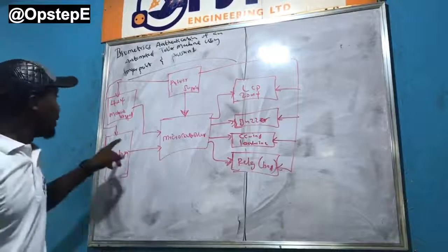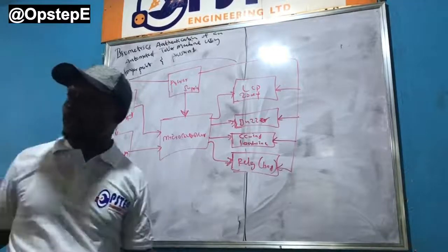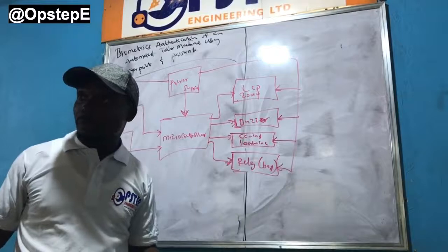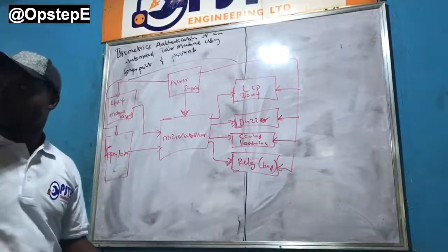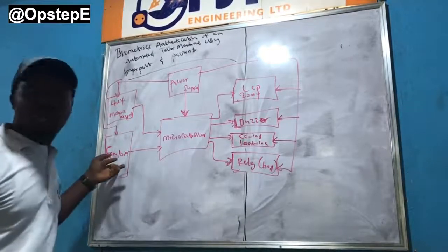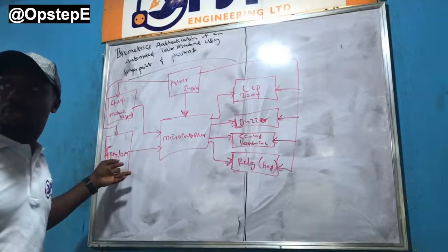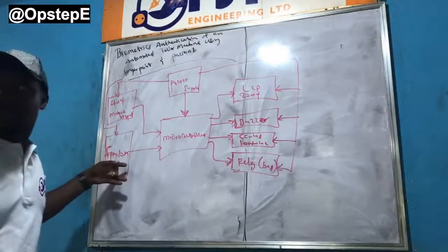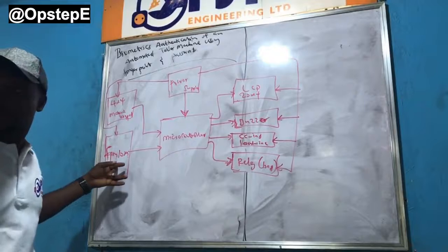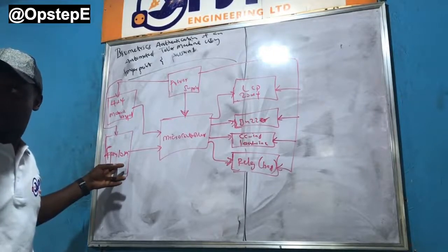For instance, the DY50 actually runs at 3.3 volts, but this one can actually run at 5 volts. So if you had not known that, or let's assume it was the DY50 we had to use, and we didn't plan for 3.3 volts, how would we have dropped the 5 volts to 3.3? We would have just ended up burning it. Did you get the point?